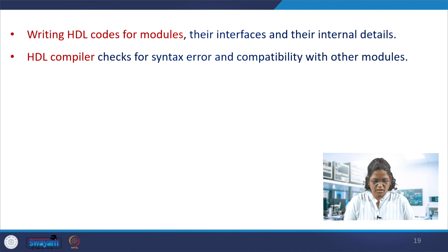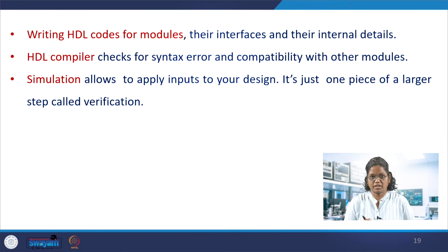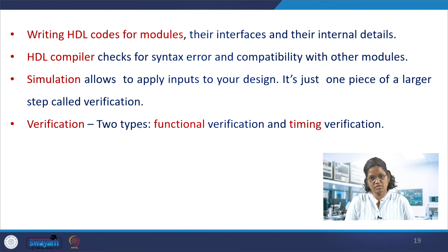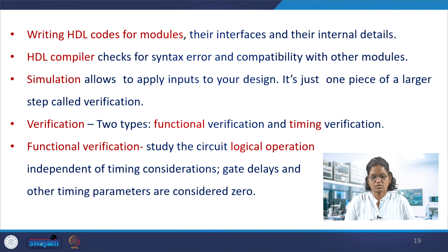We have the HDL compiler, which checks for compatibility and syntax errors. The simulator applies as many inputs as possible to your design, and it is part of the verification. As I told you, there are functional verification and timing verification. Functional verification studies the logical operation, whether it is correct or not, without considering any timing. Here the gate delays and other timing parameters are completely avoided, considered to be 0.